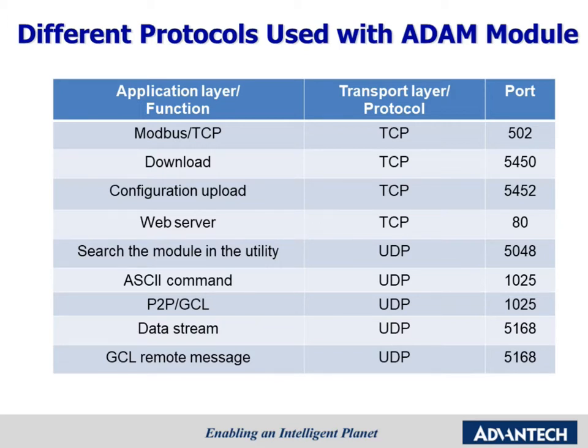If a user wants to use SCADA software like WebAccess to access the I/O status of ADAM, the communication protocol between ADAM and SCADA is Modbus TCP. He needs to enter port number 502 for data communication.